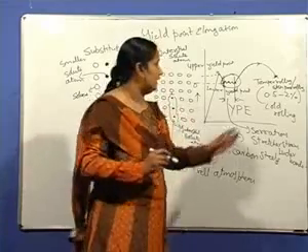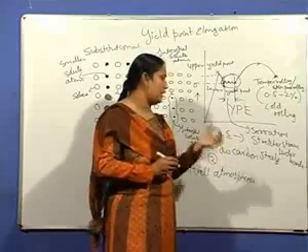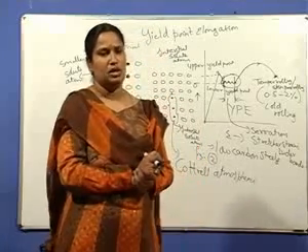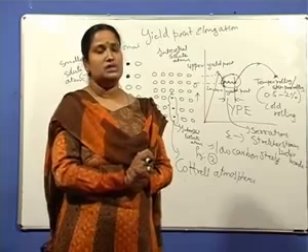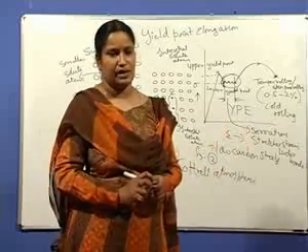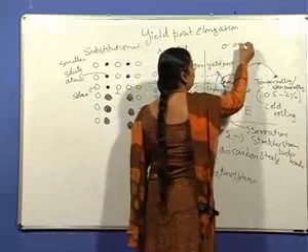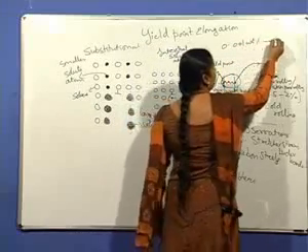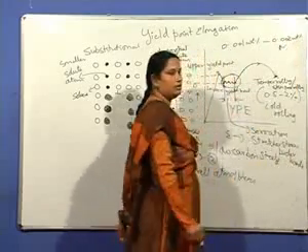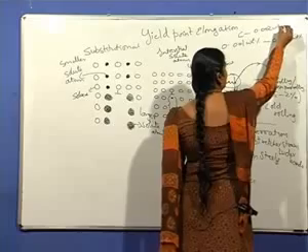For this yield point elongation to occur, only a very small amount of carbon and nitrogen is required. Carbon of about 0.002 weight% is required to cause this effect, and nitrogen of about 0.001 weight% to 0.002 weight% is required to cause this effect.